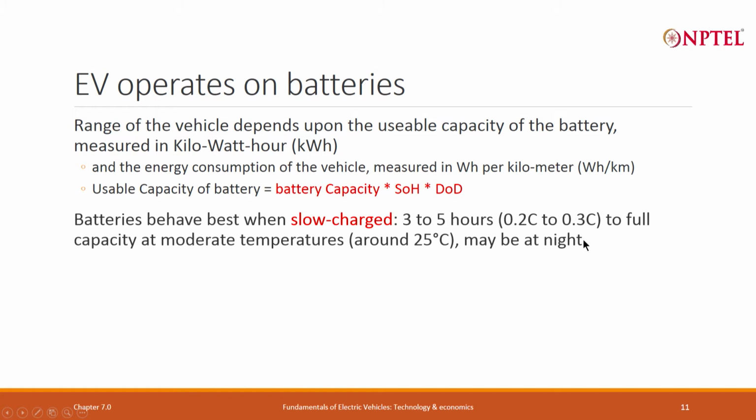So, next important thing that we have repeatedly pointed out is that you must charge always at moderate temperature and also discharge at moderate temperature, around 25 degrees centigrade. The best behavior of a lithium ion battery is at 25 degrees centigrade plus or minus 5 degrees centigrade. Anything above 30 degrees starts impacting the battery life. Below 20 degrees also starts impacting the battery life.